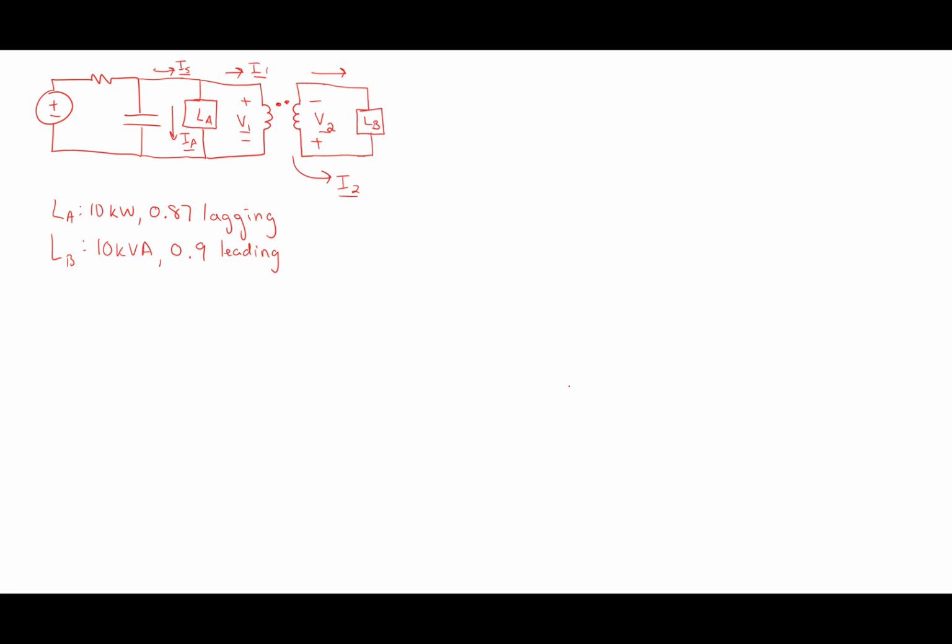Okay. All right. So what else? What have I been told by being told that it was 10 kVA? I'm told the magnitude of S. All right, not S. It's tricky. It's the magnitude of S. Okay. So I was told that the magnitude of S is 10 kVA. So if I drew the vector, all right, here's what I know: this here is SB magnitude. And I know that, all right, the other sides of the triangle there, how do I label those? Which one's P and which one's Q?